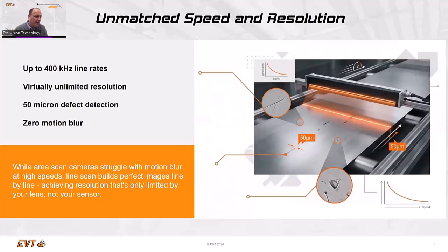If you have an area scan camera and a full illumination of an area, you get a lot of reflections. You can see here also some shadows and everything. You have these shadows in your area scan camera, and when you evaluate the image you have to deal with all these shadows and the need for perfect illumination, or maybe also distortions of the lens.